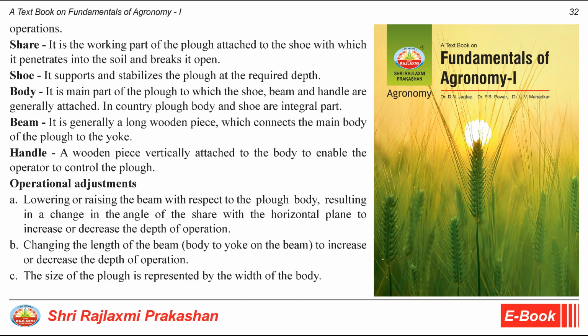Operational adjustments. Point A. Lowering or raising the beam with respect to the plow body, resulting in a change in the angle of the share with the horizontal plane to increase or decrease the depth of operation.